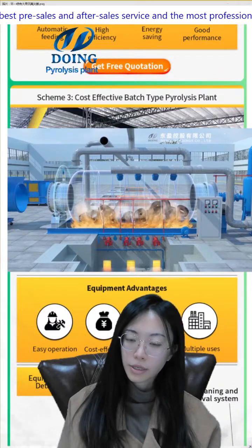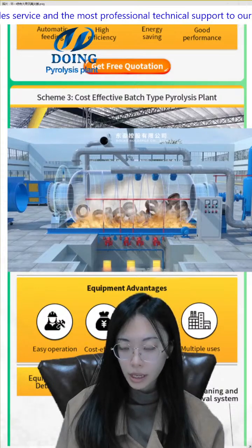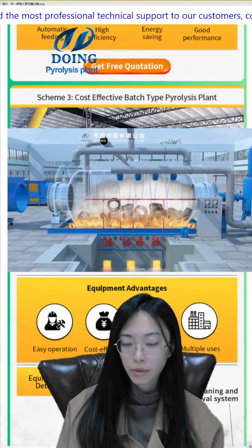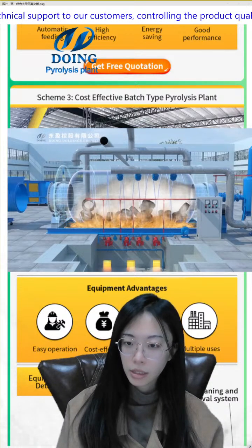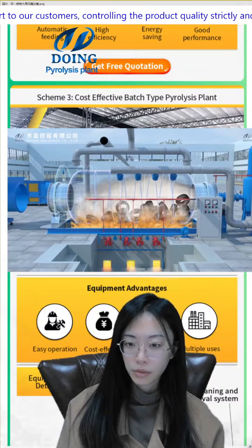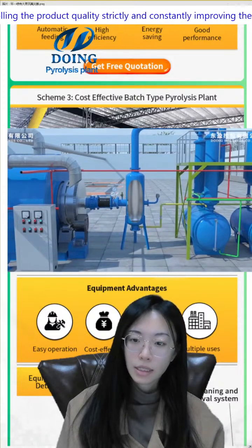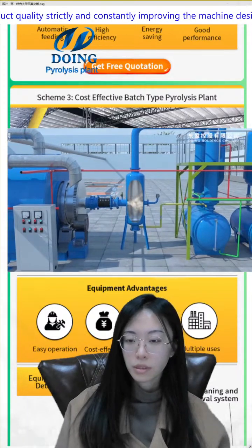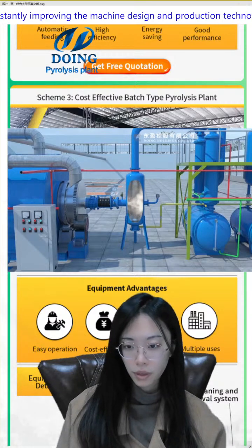Like this, in this reactor, we use 4 burners and 4 tail gas burners to heat the reactor to 280 to 320 degrees, and then we can get the fuel oil. By using this condensation system, the cooling water can condense them into fuel oil.